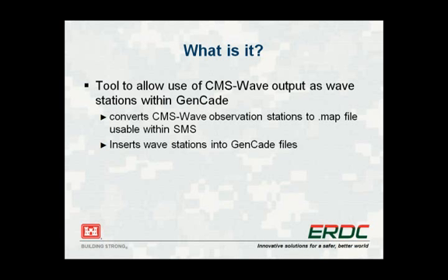Basically what this does is it converts CMS Wave observation stations to .map files that are usable in SMS, and it also allows you to insert a wave station into your existing GenCade files. So if you have a .gen file developed already, you can go ahead and just input it directly into the .gen file.